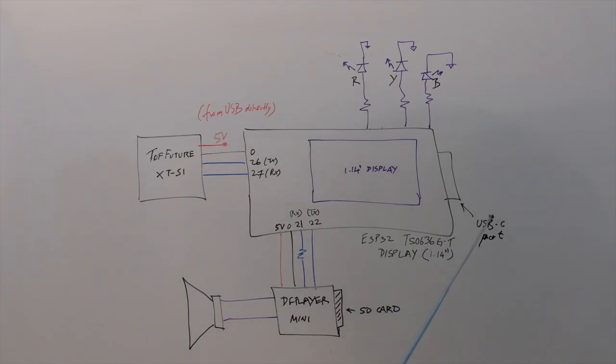Typically, the USB-C that provides the 5 volts, when it shows up on the 5-volt pin on the ESP32, is actually at 4.2 or something. So you might want to directly access the 5 volts coming out of the USB over here into this port. That's why I showed it separately as an input. You could also connect an external 5-volt supply if you have one to drive this, because this is the main part that requires a good deal of power, at least 100 milliamps I believe, to make it work. Any power voltage reduction would also degrade the range, I'm guessing.